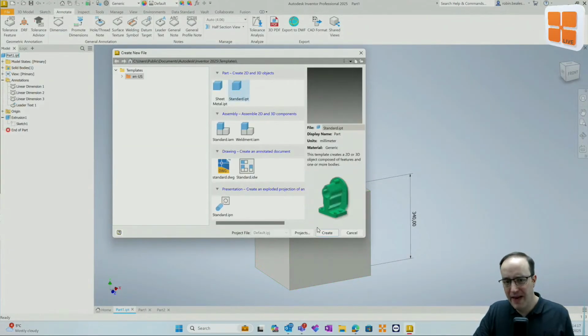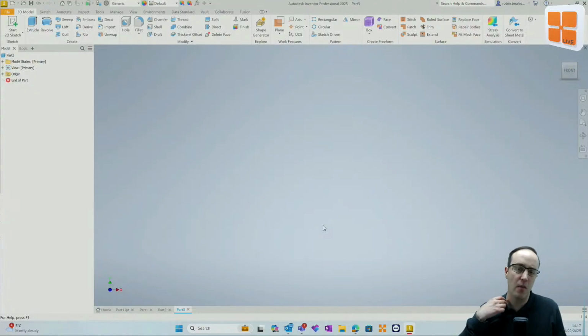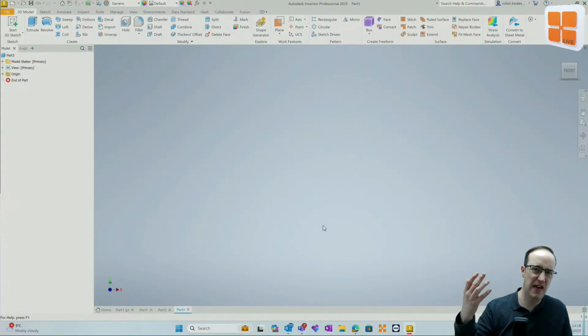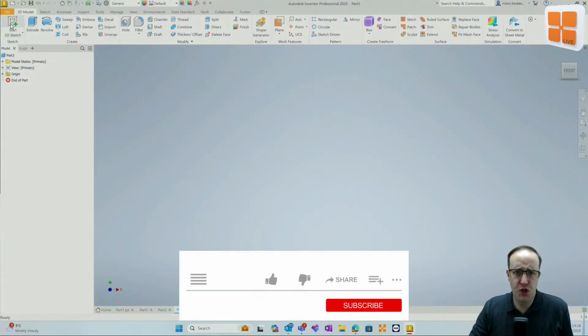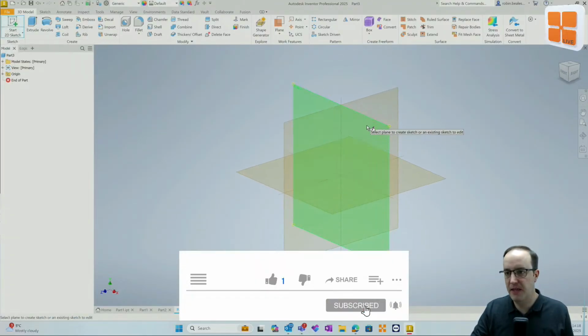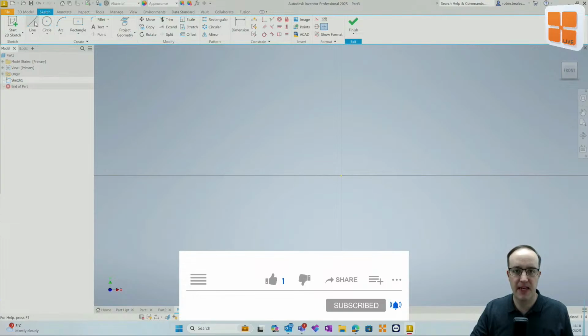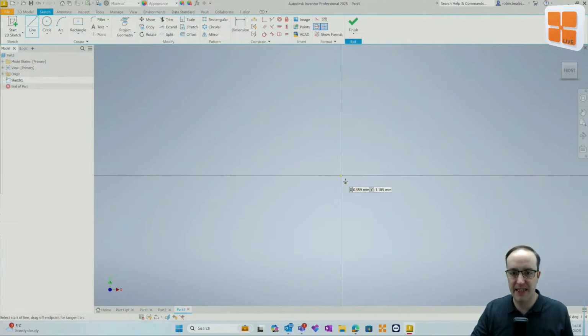Finally, if you like what we're getting at, okay, I can save some time with my annotations, but I don't really like the idea of placing the annotations or the dimensions on my 3D, just reuse your sketch dims. So let's create a sketch. Let's go onto a front view. Let's place down a line, which will make a center line. And we'll do a simple disk revolve.